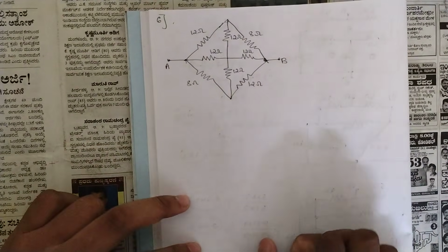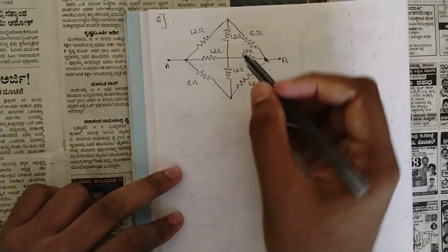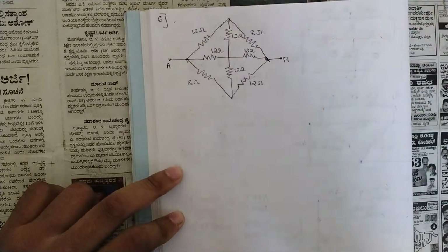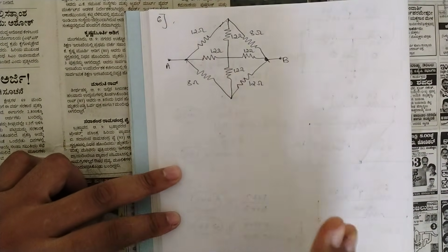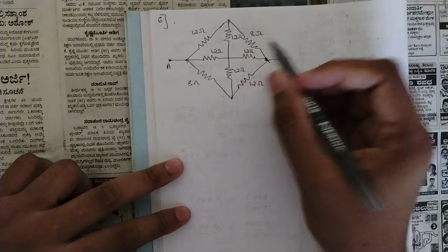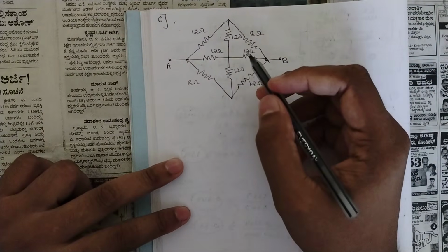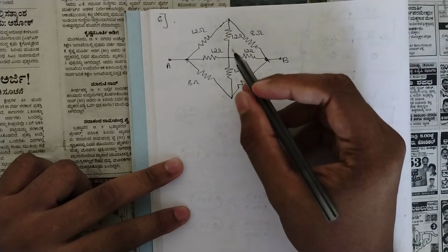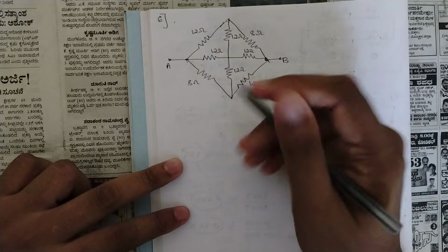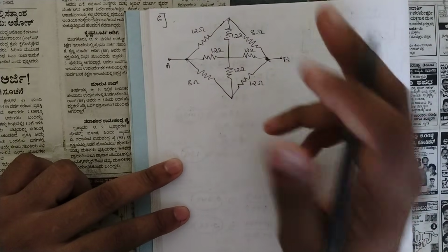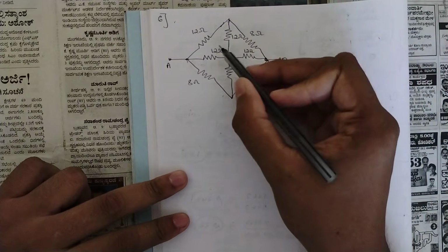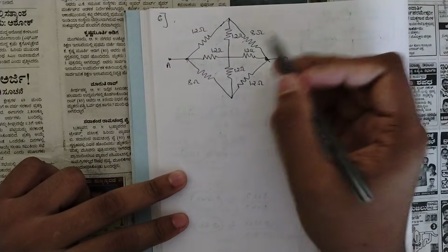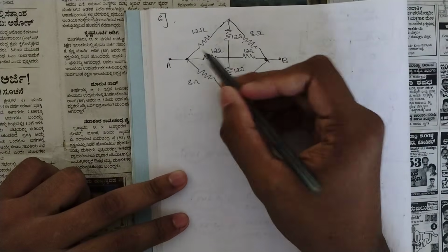So this is the next problem here. This is one diamond shape here we have like this. So this is a bit straightforward but a little bit confusing. So here again, this kind of similar problem we have solved, where we had told that we had two delta connections if you observe it, but actually we have only one in that problem. But in this problem here, if you observe it, you might be telling that we are having 4 delta connections, so you should be converting all 4 delta to star.